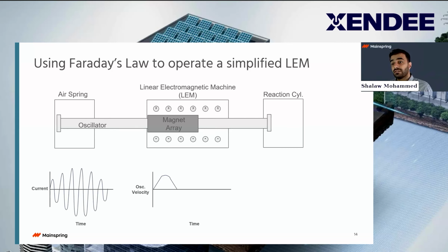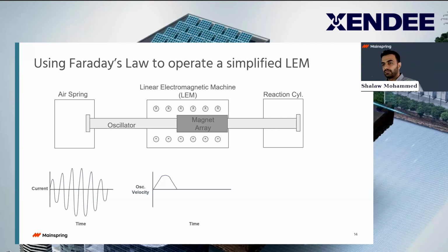Well, that's because, first of all, the system is a 12 Hertz system. Second, it is tapered off at the beginning and end because the magnets are actually at a complete stop when the reaction happens. They speed up, get to the middle where it's at high speed, and then slow down again because of the air spring toward the very end. So you have this interesting waveform, tapered off at the beginning and end. And then obviously that waveform repeats itself again.